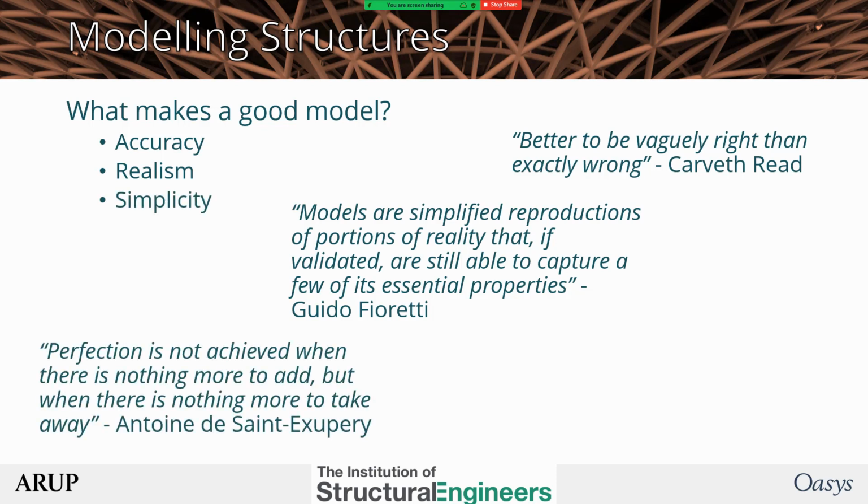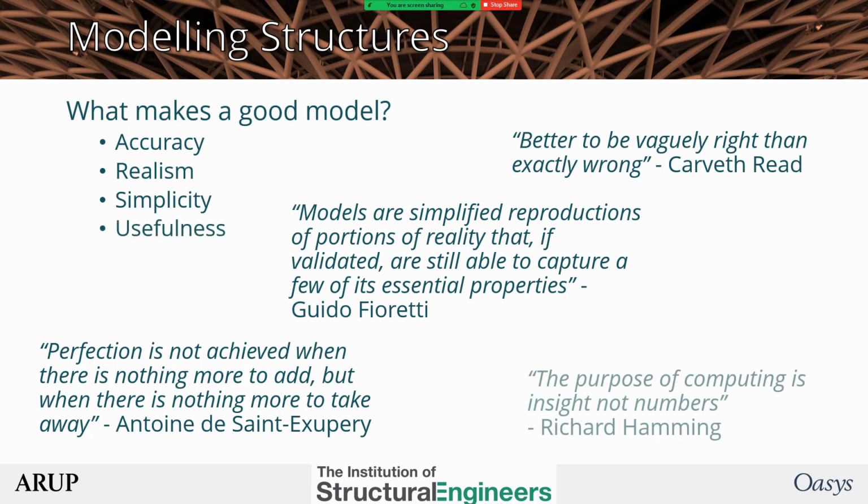It needs to be as simple as possible. Simplicity, this comes from experience. My first FE model back in university took 24 hours to run on the university mainframe. Today, I would achieve the same results with perhaps maybe only 1% of the number of elements in. It also needs to be useful and relevant. Does the model give you the answers you need? For example, static or dynamic analyses often require quite different models. So the essential question you need to ask yourself is, what is the question that I am trying to answer? Then make sure that you design your model to achieve that.